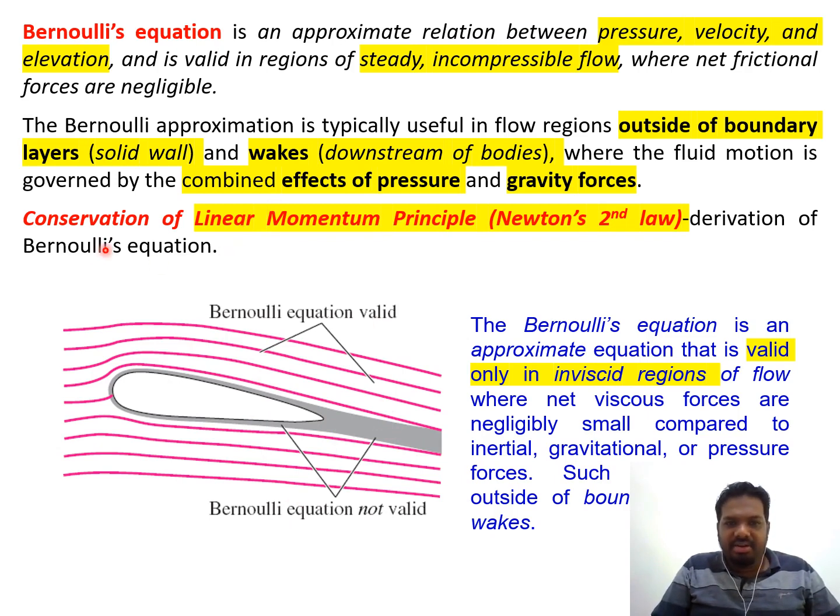The conservation of linear momentum principle, or Newton's second law, is used to derive Bernoulli's equation. It's only valid in the inviscid region. An inviscid region is a place with no friction, where you can neglect the frictional force in that particular area.